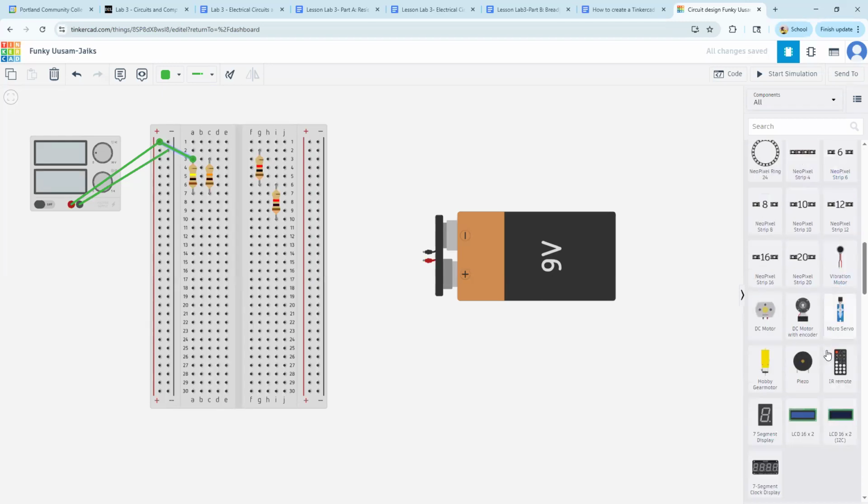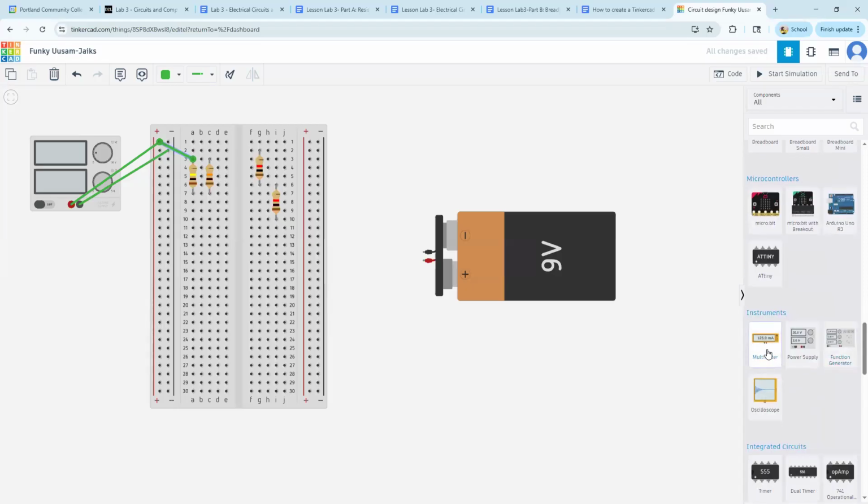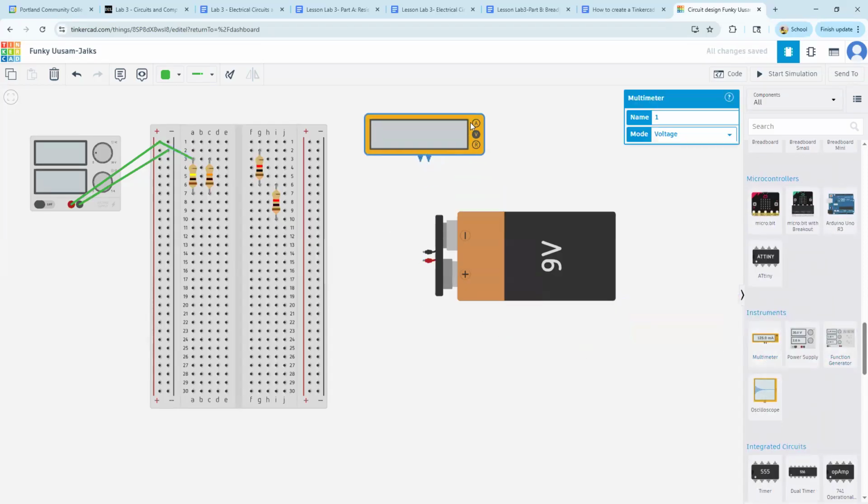You can find that multimeter actually here. This is multimeter. If I drag it here, there are 3 different parts for measuring current, voltage, and resistance. There's a drop-down menu on it, so you can change any of them. So if you want to just read the current, you go to amperage. If you want to find voltage, you go to voltage and also resistance. And as you can see here, it will be marked here. So you know if it's measuring current or voltage or resistance.